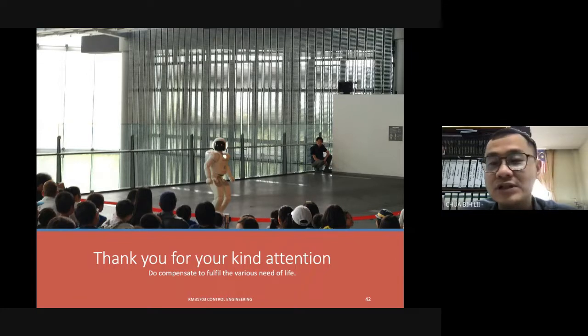There is the temperature control unit that I showed in the pictures in the last two lectures, where you can put in the P, I, and D values. Those values actually come from all these simulations. Once you are satisfied, then you can adjust it so that the temperature sensors will respond accordingly.